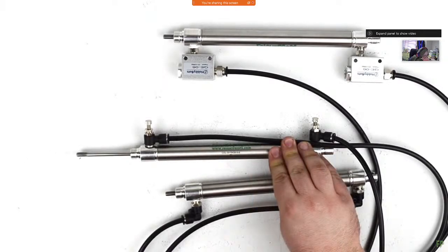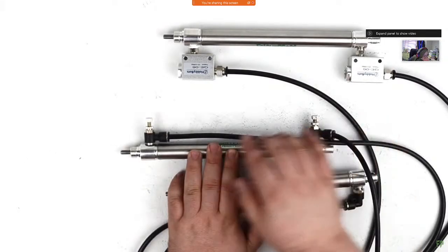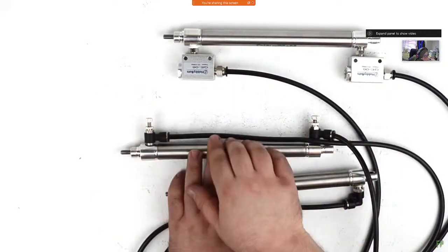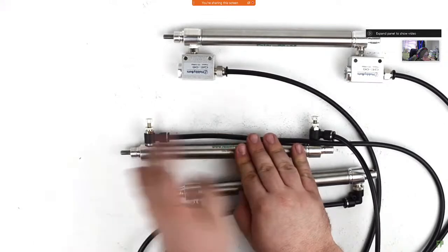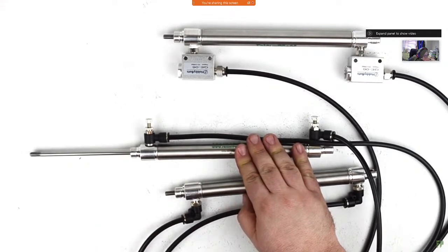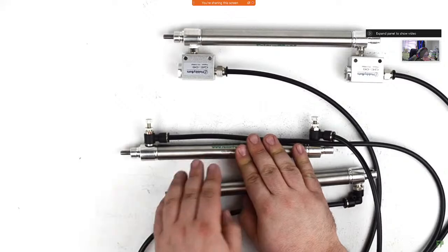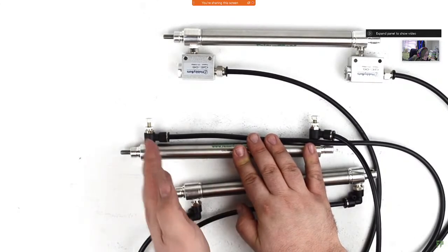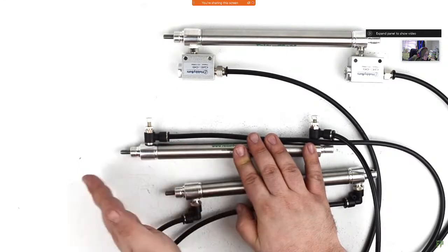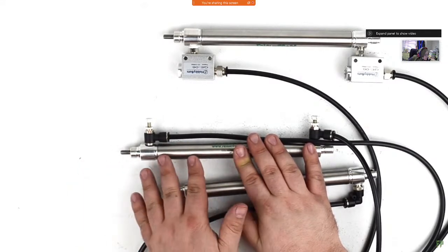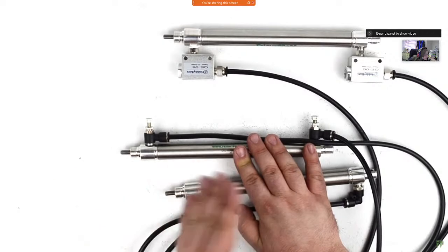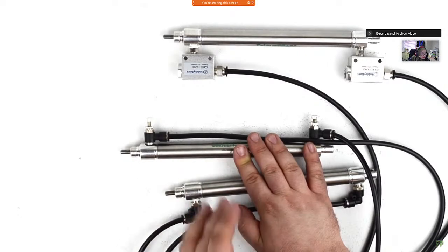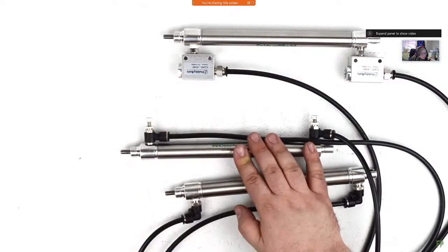So by adjusting how far these needle valves are threaded down, you can adjust the speed of the cylinder rod as it extends and retracts. One thing to note about controlling the cylinder speed is that although you can control and set the speed going in and out, you can't change it mid-stroke. So you can't have it start slow and then go fast. It's going to be set at one standard speed, and that's just the speed that it's going to operate at once you have it dialed in.